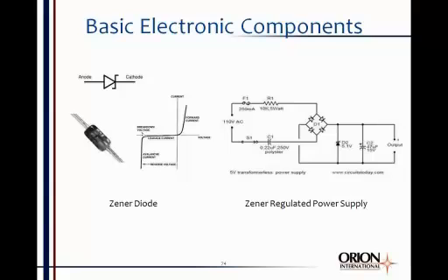So I've got 5.1 volts of pulsing waveform going out and feeding this capacitor right here, and that capacitor is going to smooth it all out. That's a filter capacitor. It's going to smooth it out and leave me with an output here of roughly 5 to 5.1 volts of fairly steady state DC. Okay, so that's what this regulated power supply is.